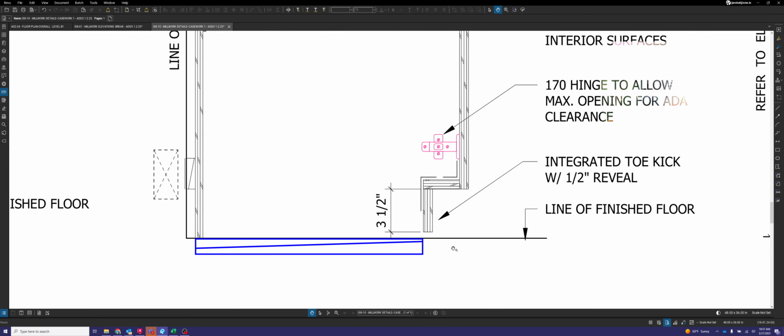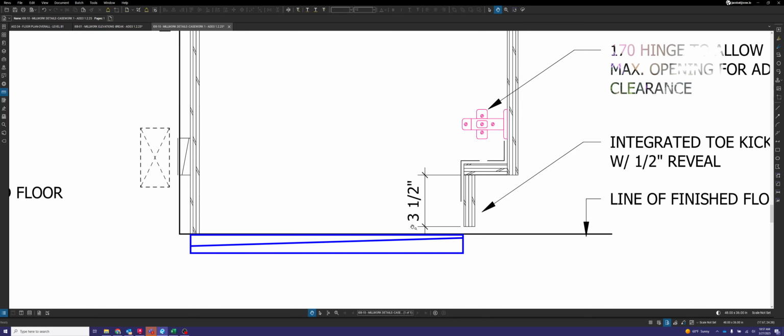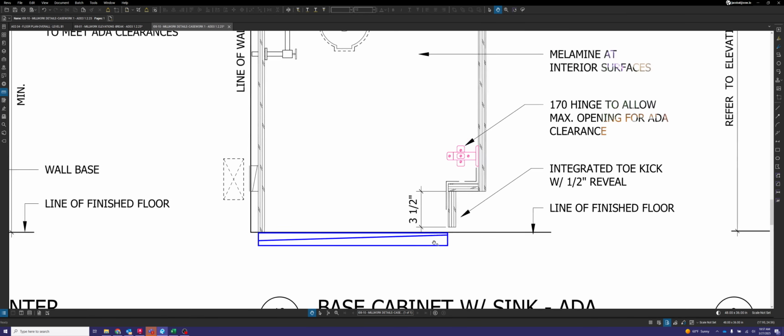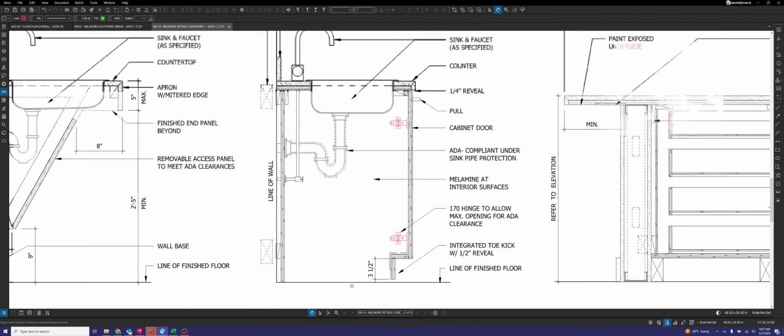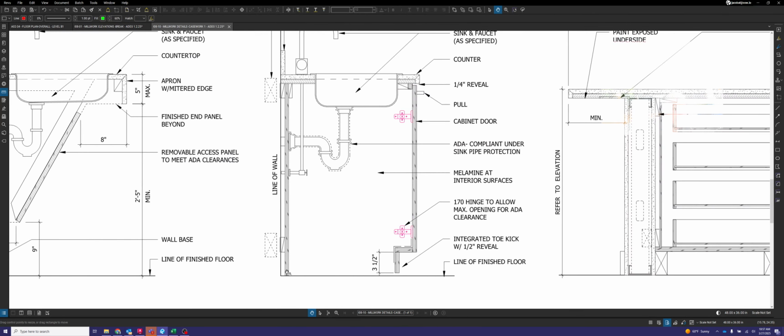These cabinets here, because they are open to the floor, are not able to use standard shim, which is why we scribe the sides and the back of these cabinets. So again, that's only applying to cabinets that are open to the floor or sink cabinets like this.